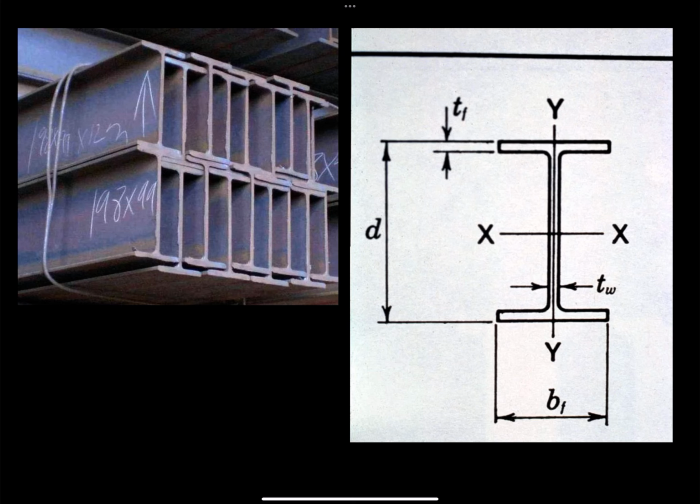So for example, a W12 by 14 is actually about 12 inches deep from top to bottom. A W12 by 336 is 17 inches deep, so that's 5 inches deeper. Both are W12s, but the increased thickness of the flanges increases the size of the W section. So there are no rules here. You have to look at the steel tables to understand the actual dimensions.